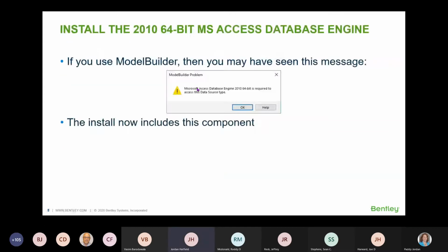All right. So this next one, if you've used Model Builder in the past, you've probably seen this message. In past releases, we have not included this component in the install. And what we found is a lot of users do not have permissions to install databases to their machine on their own. They usually have to get an admin to do it for them. So in 10.9, we've included this component in the actual install, so you shouldn't see this error message anymore.